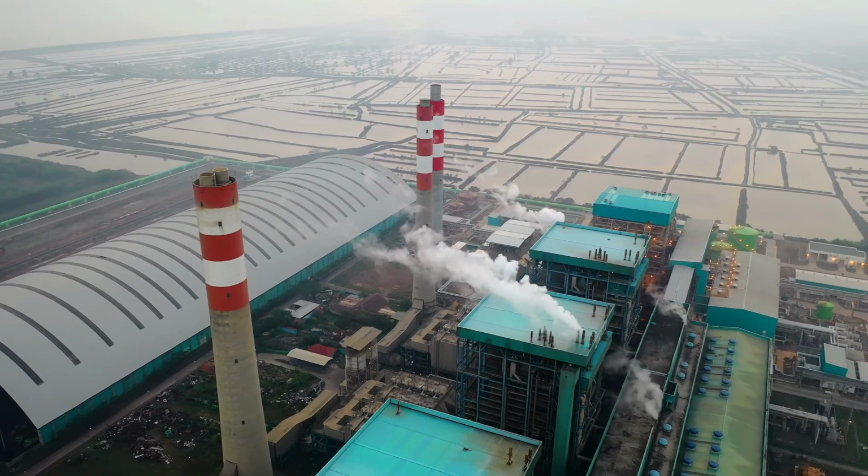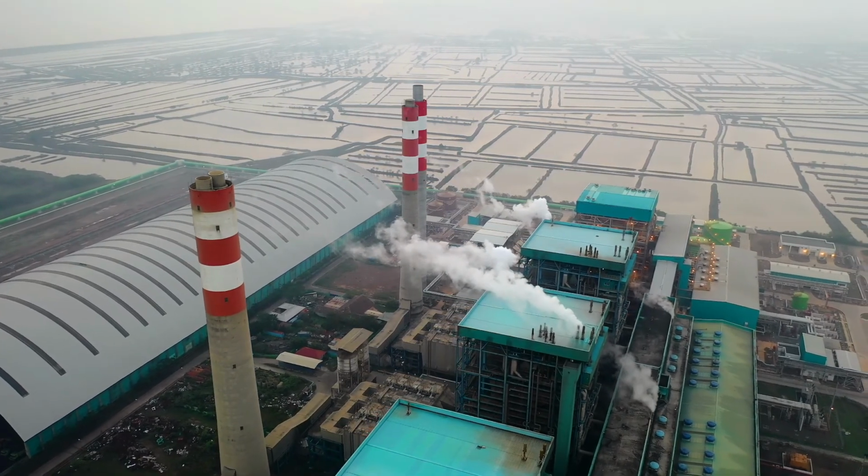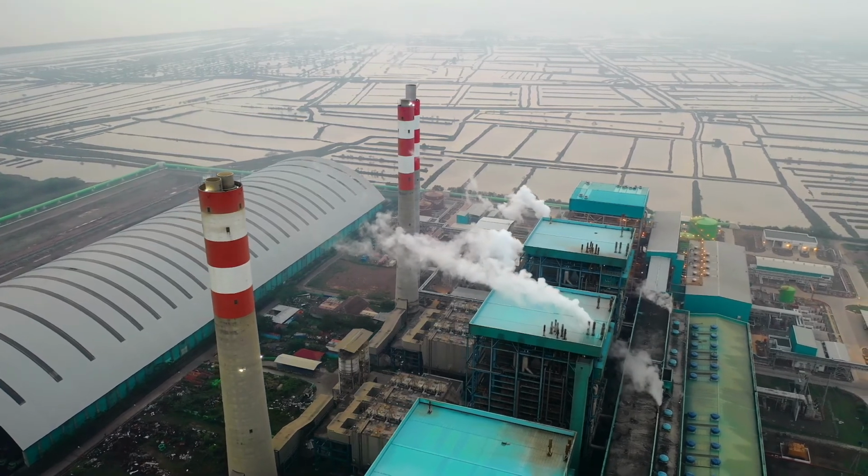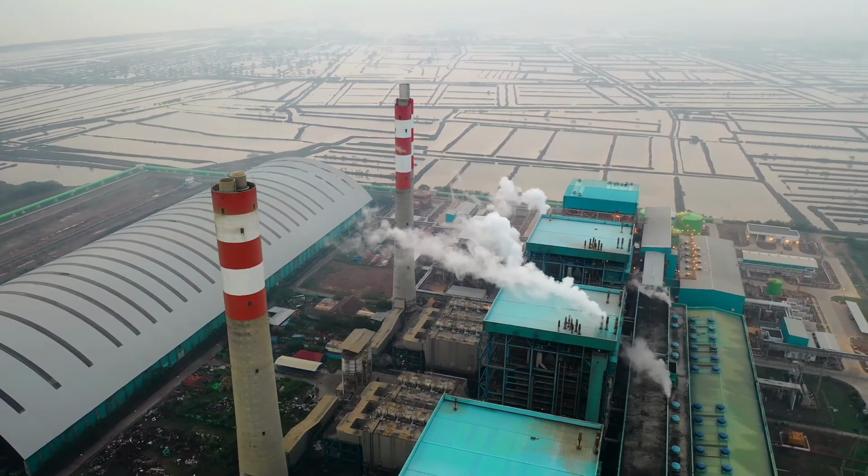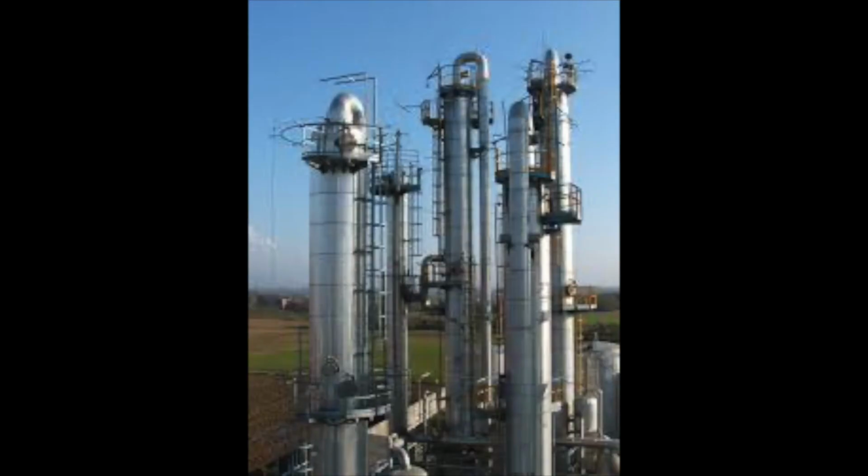So they take advantage of different boiling points of materials to heat them, turn them into gas, let the gas flow upwards, and then condense them again and repeat the process. Right, and the result of the procedure is to have a liquid phase at the top of the column that consists of the material of the lower boiling point, or the thing that more easily turns into a gas, and then have a liquid phase at the bottom of the distillation column that's entirely composed of the material with the higher boiling point, or the thing that's harder to turn into a gas. So if you slap two pipes on either end of this distillation column, then you've successfully separated the two materials, and you can use them in different places throughout your process.